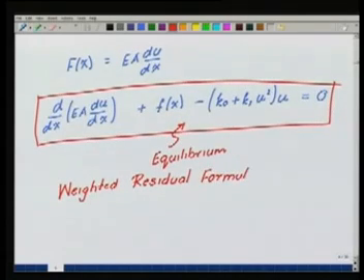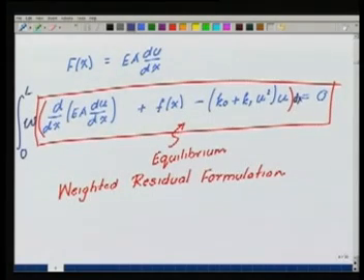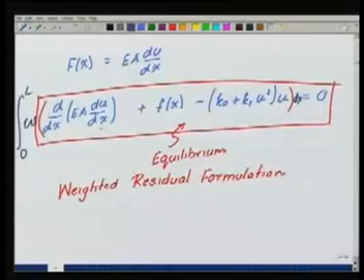Here, again we do the same thing as we have been doing till now. We take this expression, multiply it with a w and integrate from 0 to L. Put a dx here. We integrate it from 0 to L. Again we make the same arguments that here the second derivative of u is sitting. Okay, so we would like to relax the smoothness requirements on u, so we will do an integration by parts.